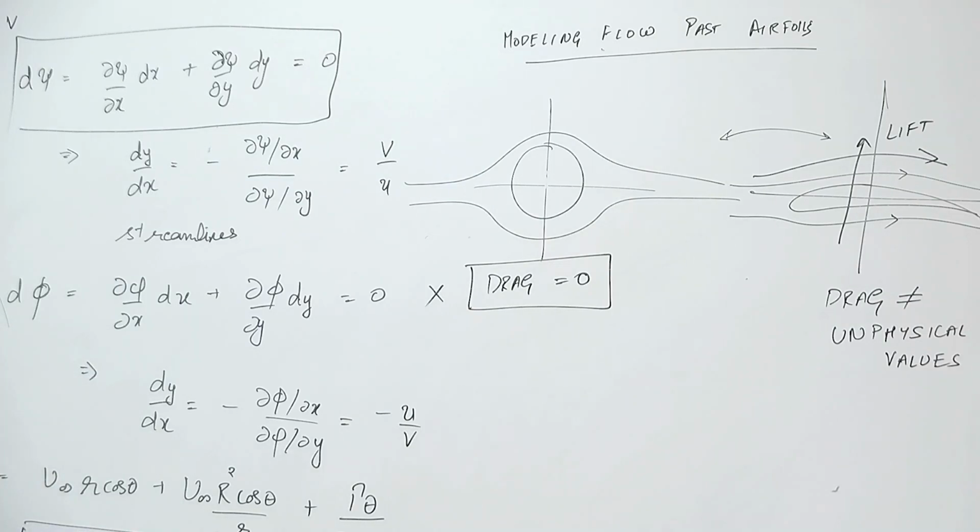Okay, but lift forces can actually be very well approximated using ideal flow analysis. And so if you don't care about putting a big enough engine in your airplane, if you can always put a big enough engine in your airplane, you are only bothered about whether you can generate a lift equal to or more than the weight, then you can basically design an airplane with your ideal flow analysis. You don't really need any viscous analysis because ideal flow analysis gives you a good approximation of the lift. Okay.